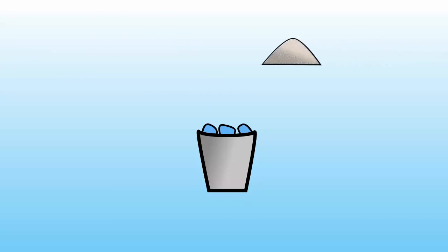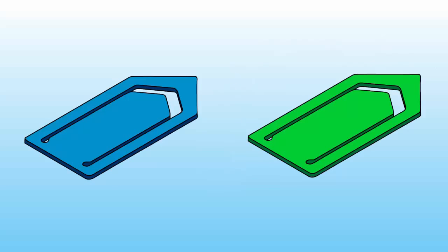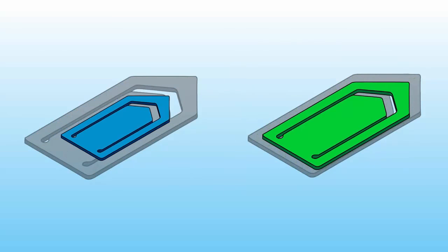The polymer's properties are determined when the polymer is manufactured and govern how the material shrinks as it cools from a viscous liquid to a solid. All polymers shrink differently. A semi-crystalline material shrinks very differently from an amorphous material. Even different grades of the same material shrink differently.